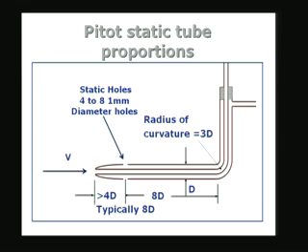We can make probes as small as 2 to 3 millimeters in diameter also. Okay? We can make very small ones, and the curvature here in the bending in this portion should be something like 3 times the diameter, the radius of curvature of the mean line. I am talking about the tube mean axis of this one should be about 3 diameters. So, the reason why we do these things will become clear once we look at the theoretical framework on which the whole thing is based.